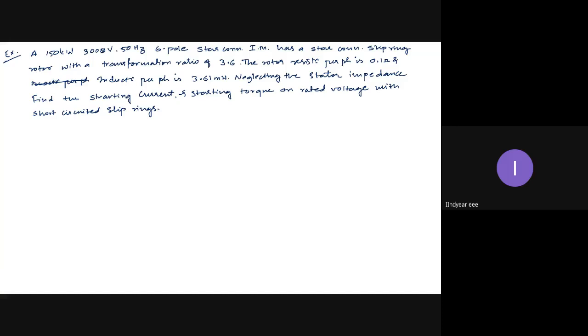Even if it is not mentioned, it is understood whenever it is asked to find the torque, the rotor must be short circuited only. With a rotor open circuit, the motor will not rotate because currents will not flow.